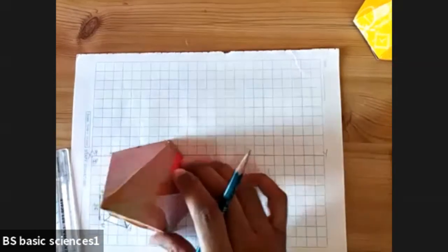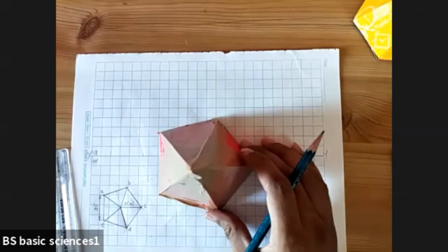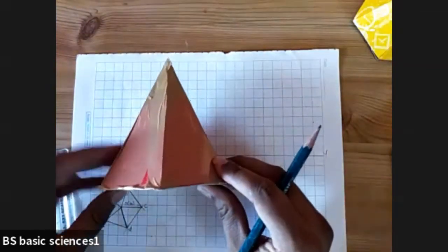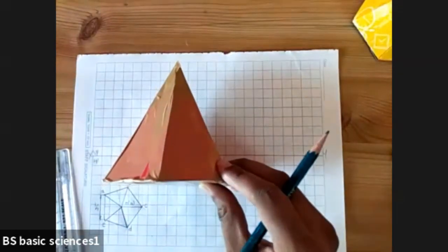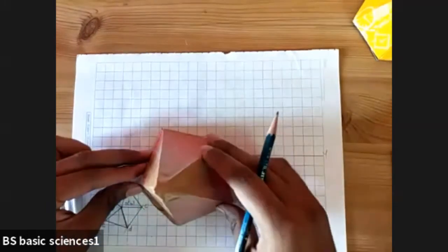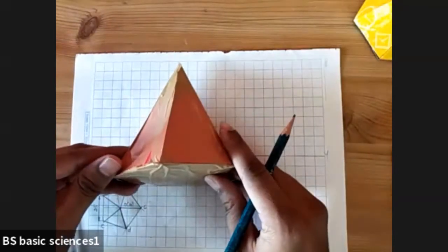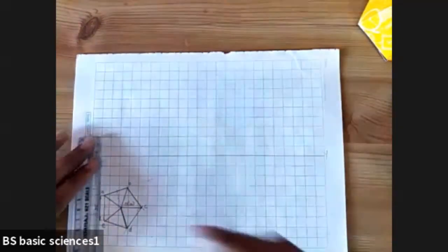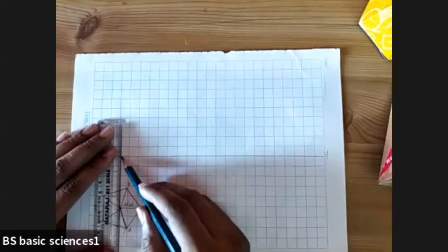Okay, this is your top view. The pentagon pyramid is placed like this. So now, what will be the front view? The front view will be like this. You can see 1, 2, and 3 edges. This is your front view. So if you want to view the top view, you'll be rotating like this. So in the top, it looks like this. If you want to look at the front view, we'll be placing the pyramid like this: 1, 2, and 3. Fine. We will draw the front view of the pentagon pyramid, which is resting with respect to the edge.